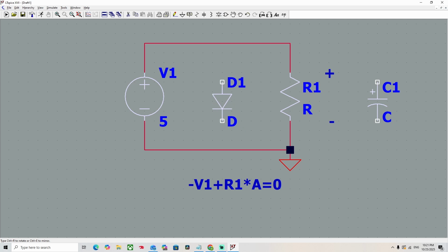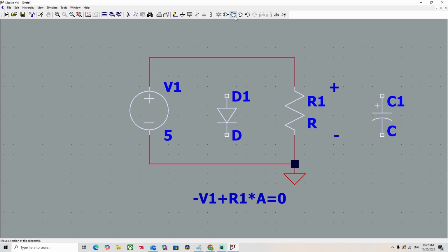Diodes are polarized, for example. The quote-unquote positive side of a diode is typically the large flat triangle side, and this is just for a basic diode, and this would be the negative side, where current would flow from top to bottom, not the other way around. If you were to rotate this around, current would not flow this way. It wouldn't blow up, it would just not ever flow this way. So you basically would have an open circuit from here to here if you were to connect wires.